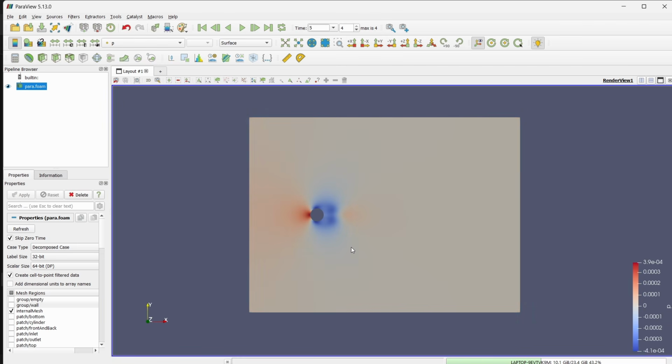So if you let it run long enough, you will also get the CL data, which will allow you to calculate the Strouhal number directly. So it's up to you. It's up to the post processing. Maybe I'll try to make a video on how to do the fast Fourier transform for OpenFOAM.